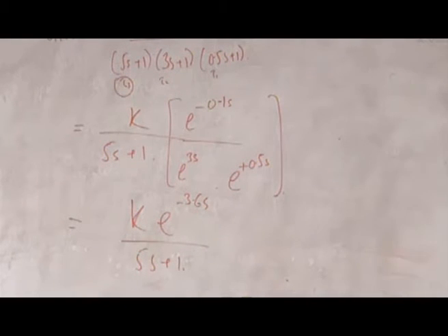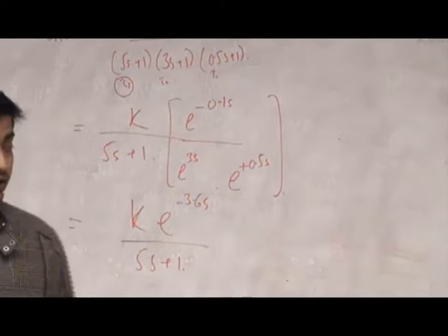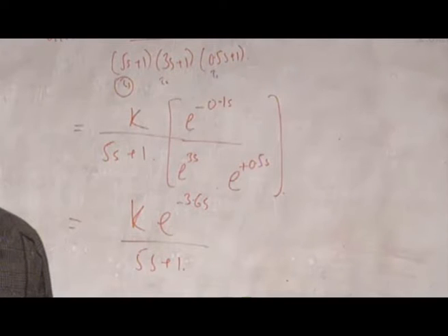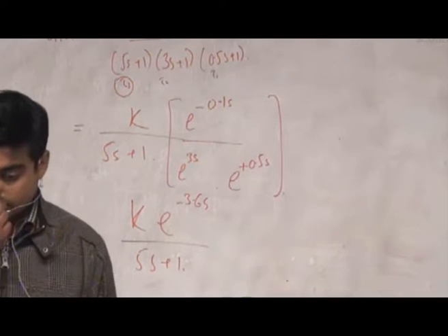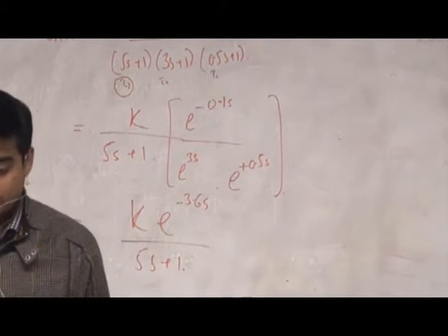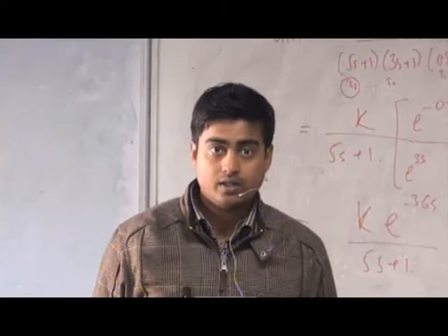When we consider the stability, if we have right hand side poles in the transfer function, then only it affects the stability, in the sense that your system will become unstable. So the order of the system does not affect the stability in the usual sense that your system will turn into an unstable system.